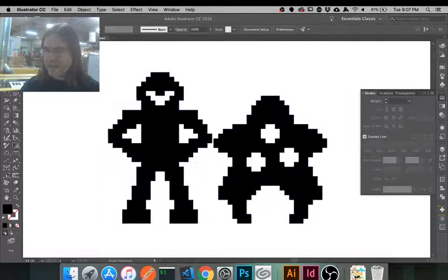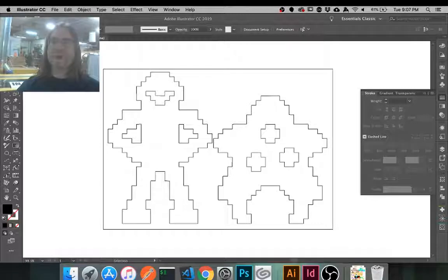And I like to go into what I call, you press Command Y, I call this reality mode. Now reality mode is about just toolpaths. Let me explain the distinction here. Let's say I was going to print this out on a piece of paper. Well, that's just artwork. That's got a lot of different colors. It's got stroke thicknesses. It's got special effects. That's for printing on actual paper.